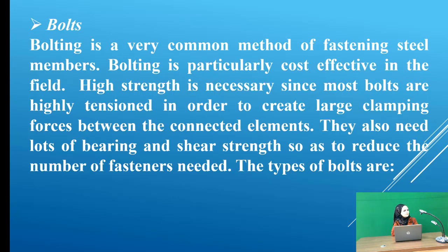Another part which is important in steel construction is the bolt. Bolts or bolting is a very common method of fastening steel members. Bolting is particularly cost effective in the field. High strength is necessary since most bolts are highly tensioned in order to create a large clamping force between connecting elements. They also need a lot of bearing and shear strength so as to reduce the number